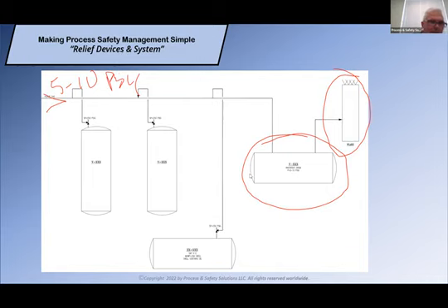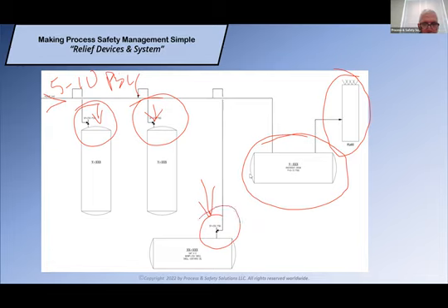So again, you have back pressure on each one of these valves, and back pressure here on each of those. So making sure that we're taking into account each of those back pressures here, especially if that's somewhat variable, then you need to take that into account. Conventional relief valves may work fine here because everything is set at 250 and we've got a constant back pressure. If that pressure is constant, then we can adjust the springs accordingly.